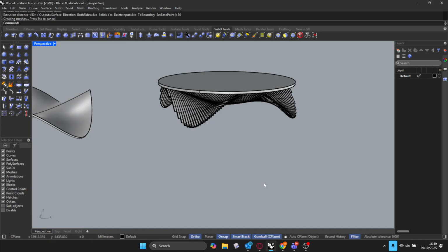Okay? I'll let you have a play around. We have a few minutes, and I'll come around and help anybody that has any questions about that. Does that make sense to everybody? Is that helpful? So I want you to now just have a go, just for the last 10 minutes. Just have a quick turn at creating contour curves. So create a sub D, create some contour curves through it, try to extrude them, try to extract a wireframe, and do a multi-pipe. Okay? And I'll come around and help anybody that might be struggling.